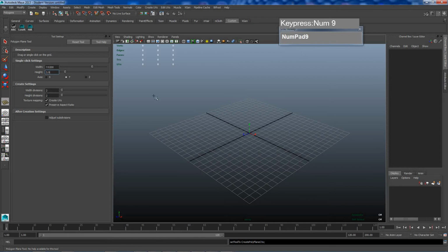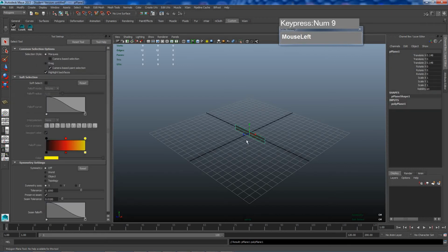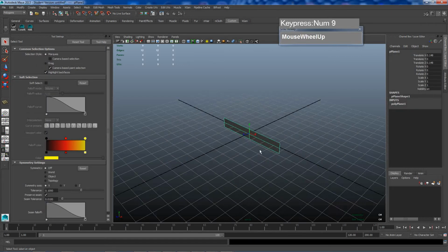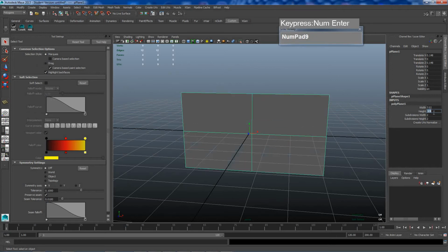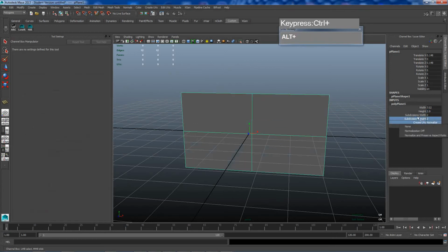Now before I click on the plane, I want the image plane to be facing me in the z-axis, so I'm going to click on the z-axis option, and then click to create the plane. Okay, something is wrong with the plane dimensions here, so let me go to the inputs and see. The height wasn't registered, so I remember the value was 3.9. I'm going to click on the value to enter it. The divisions, I'm going to change to 1 by 1.